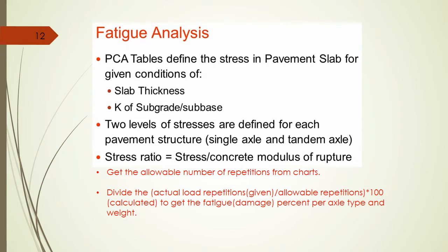Now let's talk about the fatigue analysis. PCA tables define the stress in pavement slab for given conditions. So the stresses that arise in the slab are a function of slab thickness and modulus of subgrade or subbase.